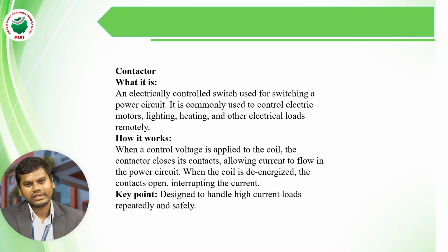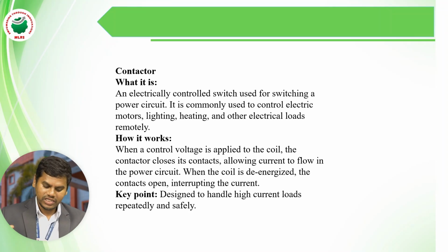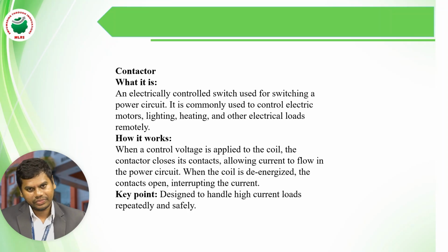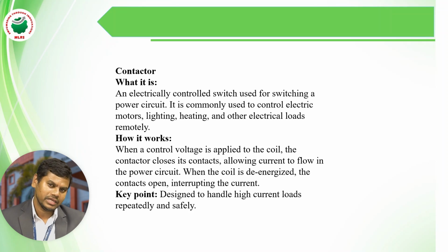So what is a contactor? A contactor is nothing but an electrically controlled switch, and it is used for switching a power circuit. It is commonly used to control electric motors, lighting, heating, and other electrical loads remotely. Here, the electrical loads can be many kinds: inductive loads, resistive loads, capacitive loads.